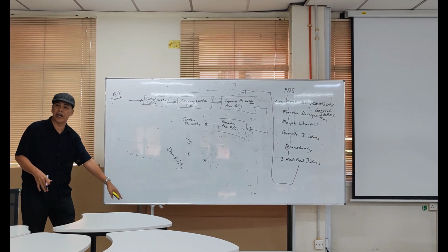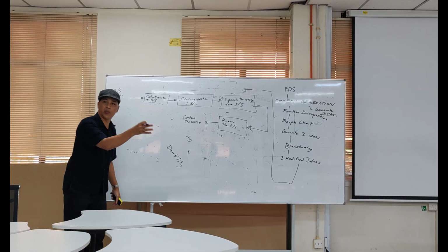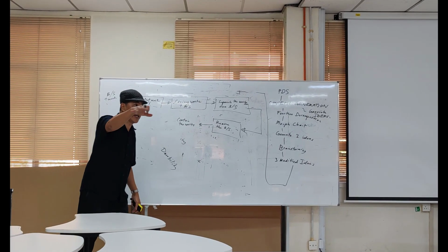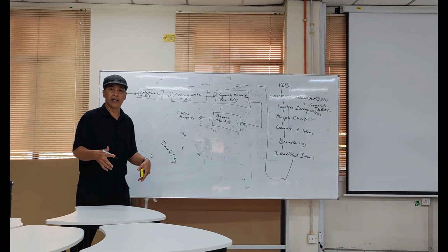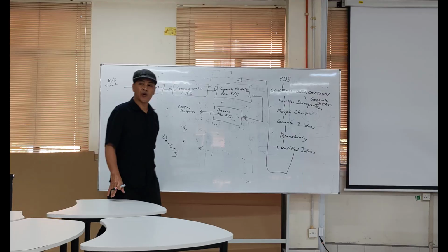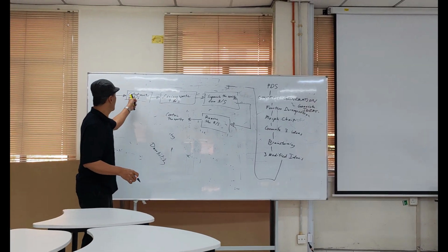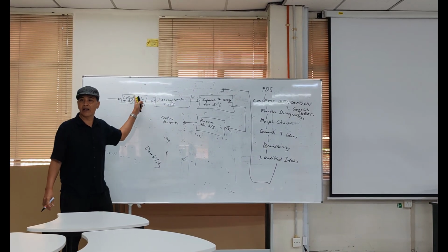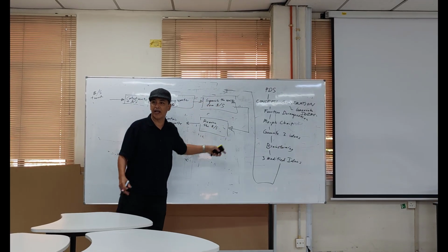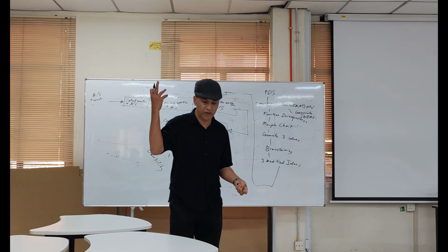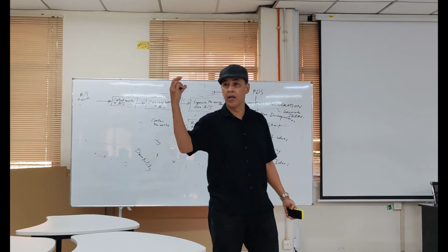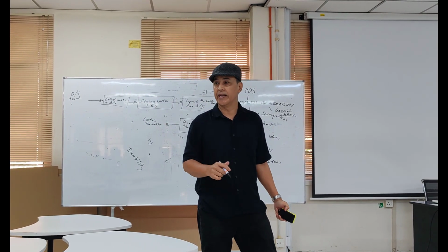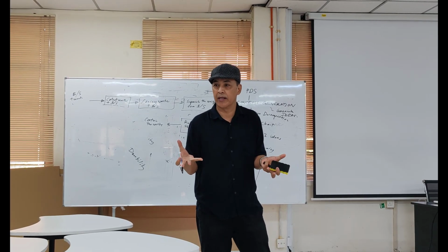Then they make a morphological chart. They throw all the possible alternative ideas into the cells. We have already done this, right? Then generate three concepts, brainstorm, make a modified concept. Now you need to evaluate which concept is the best. So you don't throw this away. All these things are functions that need to be evaluated. So instead of putting just a single word as your criteria, like "functional", that is too vague. Understand me? Too general, too subjective.